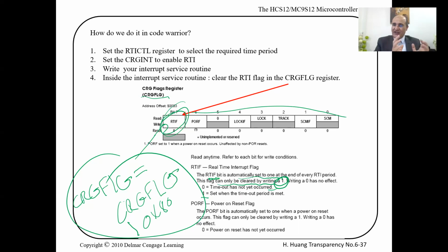Okay. So to create a function that is based on an interrupt, a hardware interrupt, we call these hardware-based delays. And we use the interrupt service routine to keep blinking the 7-segment display every second, for example, or do anything else.